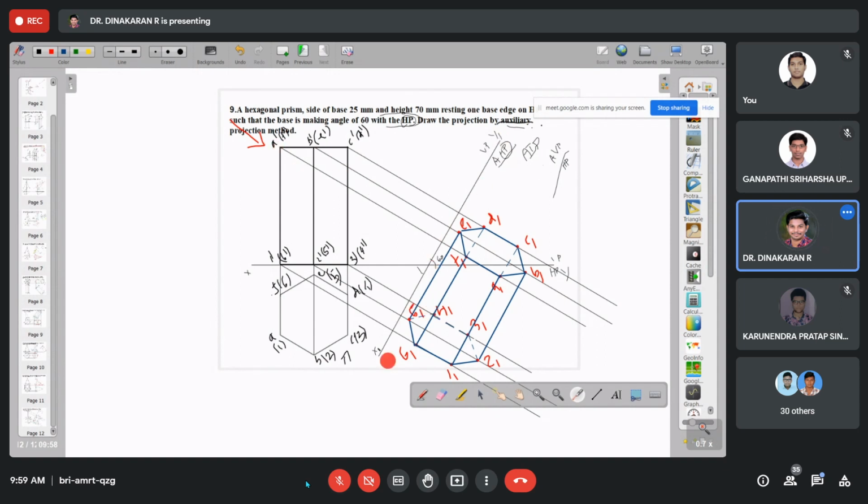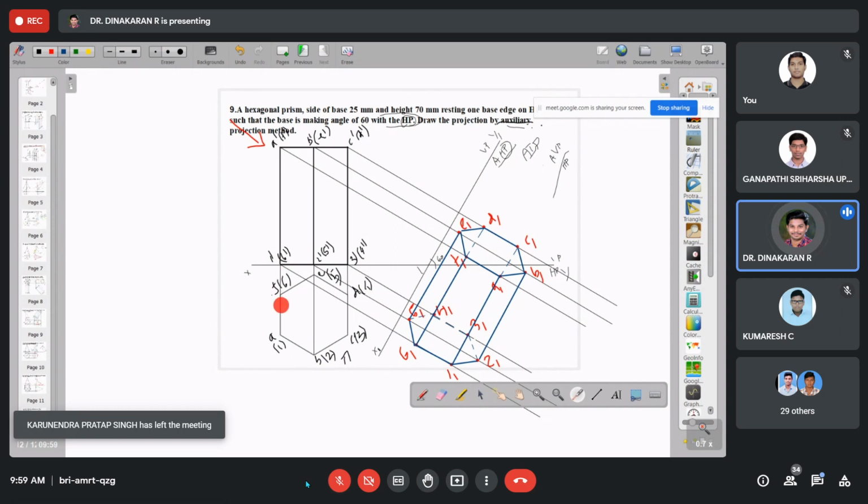Then after drawing the perpendicular lines, at 90 degrees, from the XY line measure the true shape dimensions: how much A, how much B and C, and the same way D, E and F. Then the measured dimensions are converted through the new reference line. If XY line to A1 is 42 mm, from this one, which is the 0 line, mark 42.